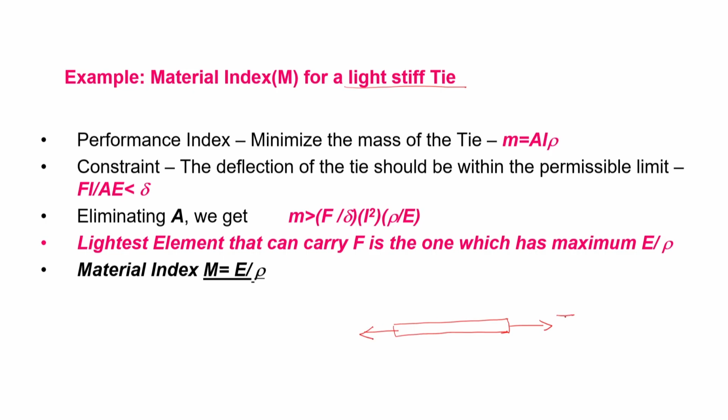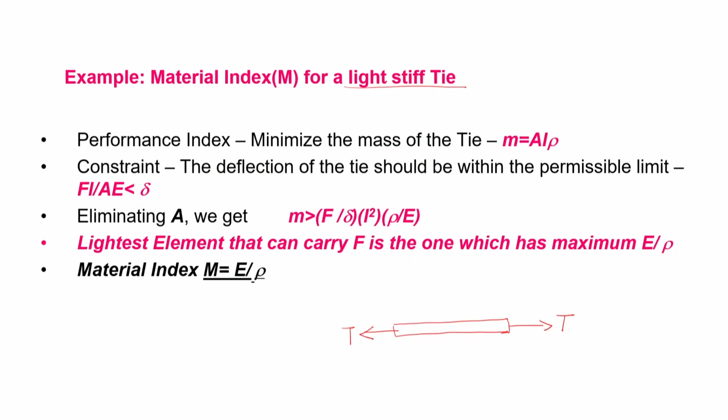Okay? So, there is tensile force, right. So, if I take this member and make sure that I am only pulling it always, then this becomes a tie member. So, let us say I am trying to see a tie member, but it has to be stiff. What does stiff mean? It means it must have a very high modulus of elasticity, and also it has to be light.